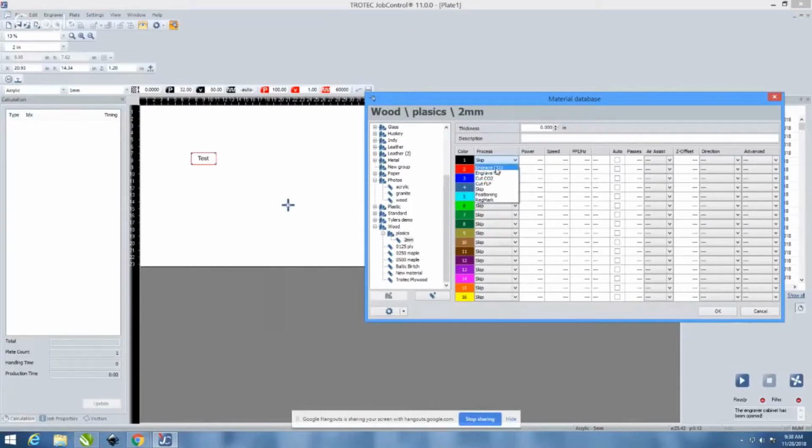Yeah, sure. So we do have a few selections here in your drop-down menu. Engrave with your CO2 laser means you would be engraving with the CO2 laser source in your laser. If you're engraving with the fiber laser source, you're engraving with your fiber laser source. If you have a flex laser. If you don't have a fiber or flex, you won't have that option. This is cutting with your CO2, cutting with your fiber laser. So maybe for kiss cuts or something with your fiber laser there.